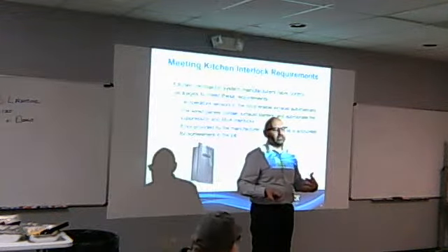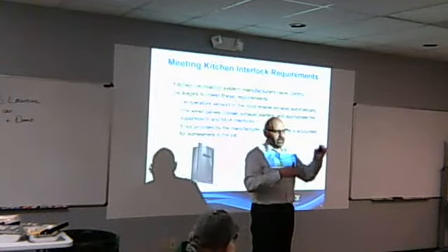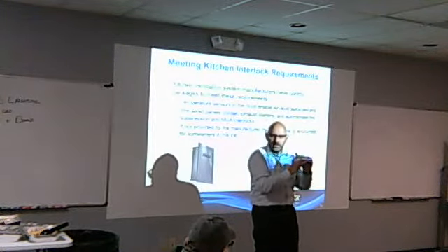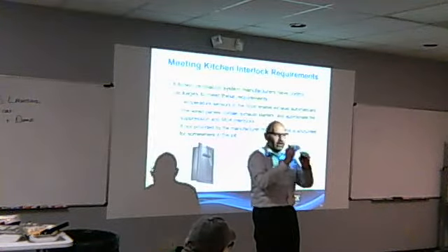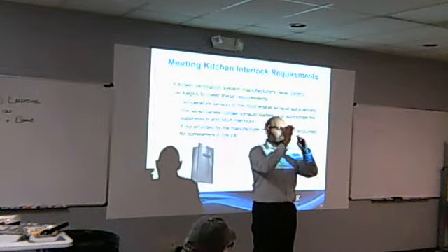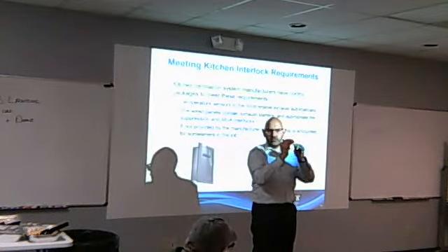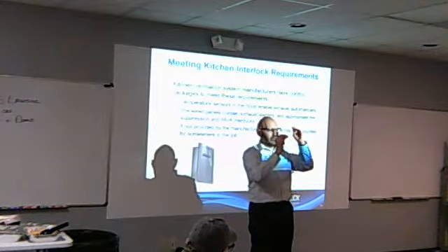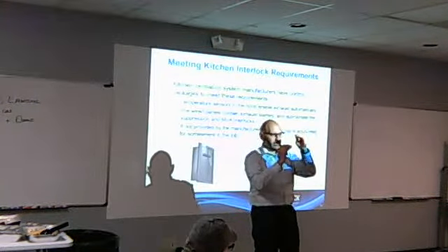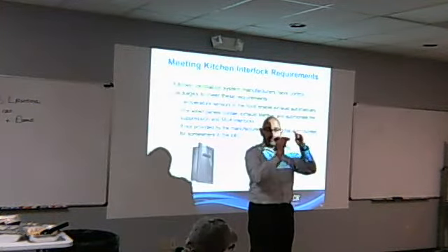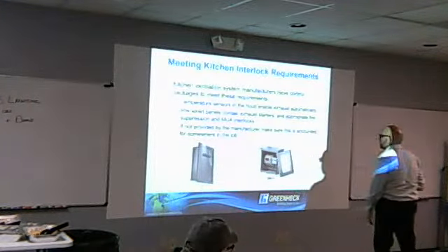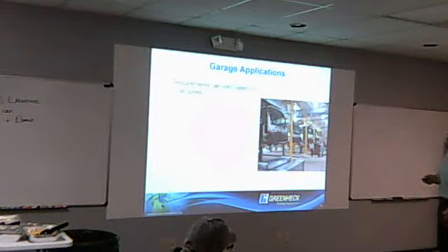So we have systems in place that have a variable volume and say, okay, wait a minute. If they're not cooking and we don't sense X degrees of heat, turn down that exhaust, turn down the makeup air, and those two will just track. You always want a kitchen a little bit negative. So if you're exhausting 5,000 CFM, maybe you're only supplying 80% of that. As the exhaust comes down, supply air comes down, so you're saving energy both ways with variable volume.